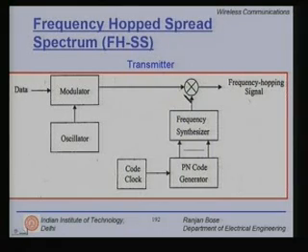Now the question is, on which of the subbands, which channel, must it be sent? So you have a code clock which generates a PN code sequence, and then according to the PN code sequence you generate the frequency, up convert and send. So as I jump along my PN code, I jump along my frequency band. The PN code tells me which subband to choose for onward transmission.